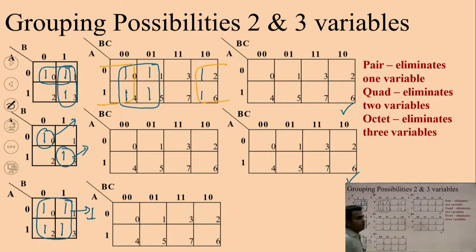So if there are entries exactly opposite on the edges of the K-map, either on the left-right or top-bottom, these entries can also be clubbed into a single group. Okay, so proceeding further, if there are these kind of entries, let's design grouping for that.